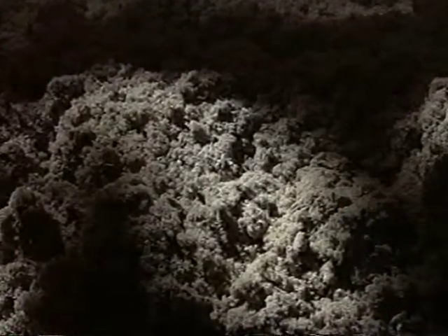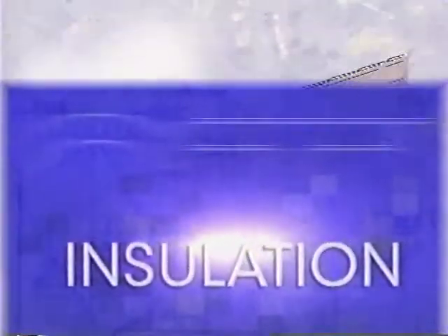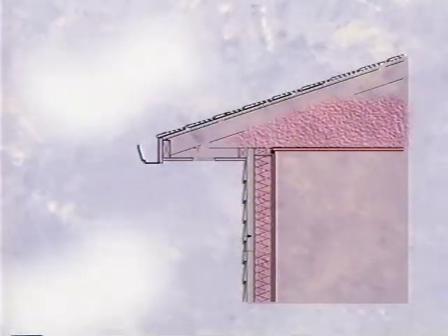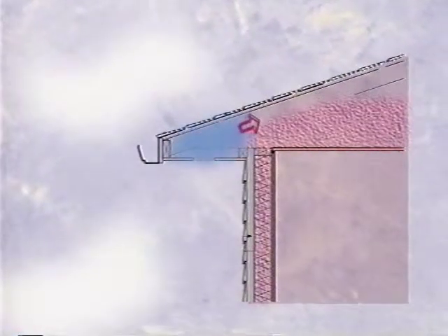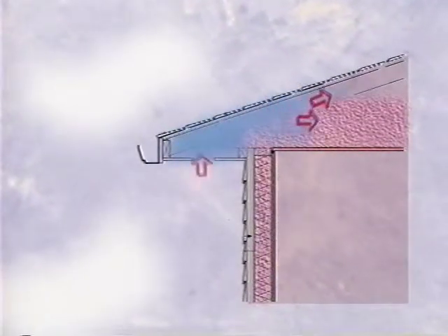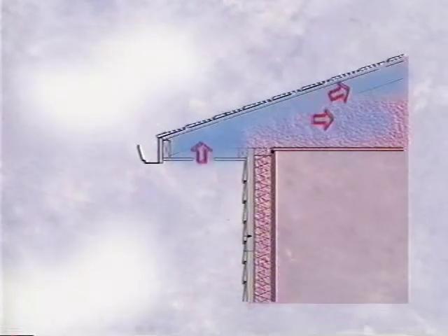Insulation of attics is extremely important. Here we must balance proper ventilation with proper insulation. In a typical attic, you will find insulation pushed to the outer edge, exposed to the outdoor air which comes in through the soffit vent. Because insulation is not an air barrier, the wind can enter the insulation and leak into the conditioned space. This problem is known as wind intrusion.